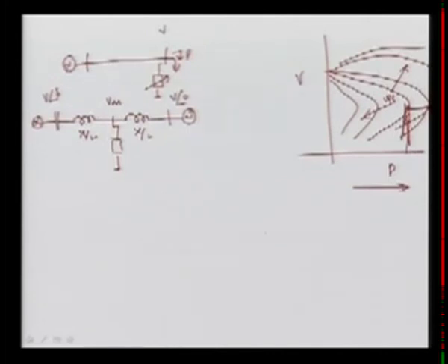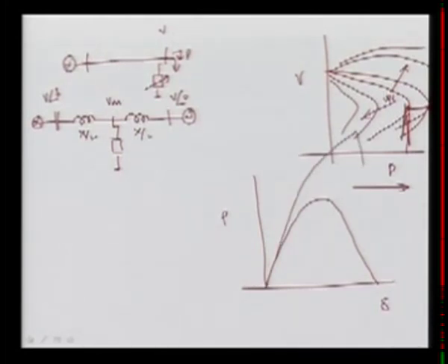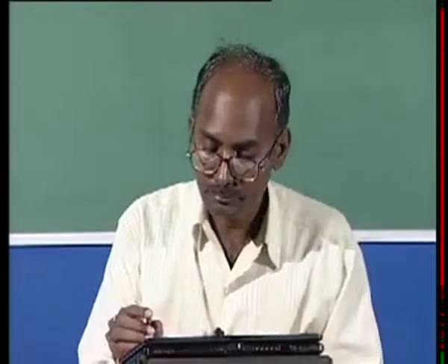for this case? Now let us draw here again the P. For the transient stability it is always an angle, here it is your power angle that we normally discuss. So this is your P delta curve, let us suppose in the normal case. Now I said that if we are going for the midpoint compensator, our characteristic is going to be double of this. So this is when we are putting the compensator and we are trying to maintain the midpoint voltage equal to the sending end voltage, from the fixed voltage.